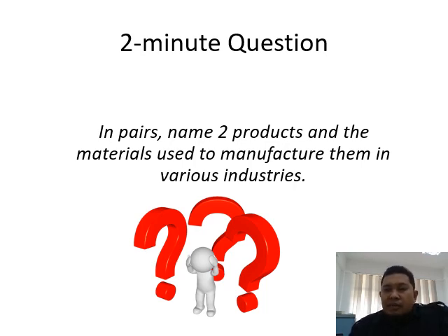And then inside it, when you have the ink, you need to use polypropylene. It is easy to mold and easy to inject the ink inside it. Of course, you need to consider chemical resistance, and the ballpoint of the pen should be made from, I think, a stainless steel alloy.